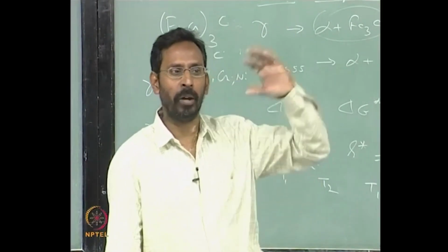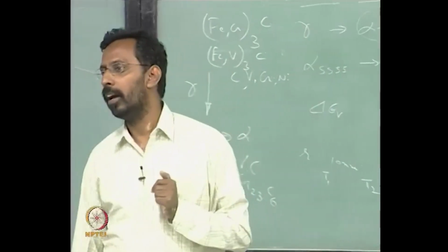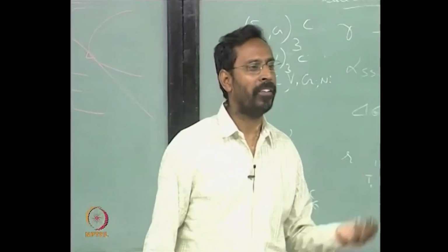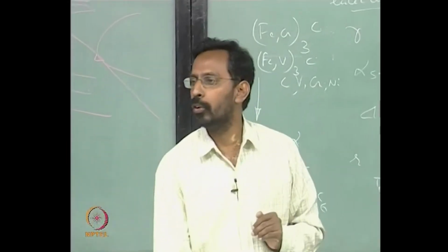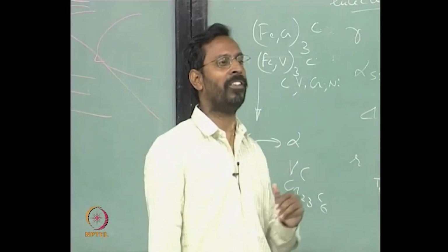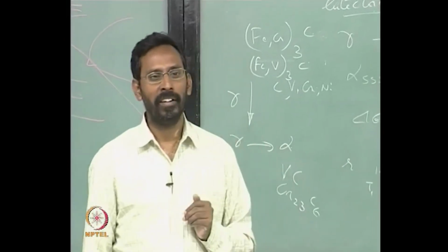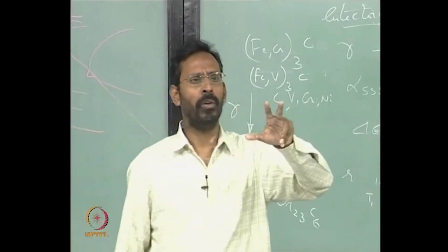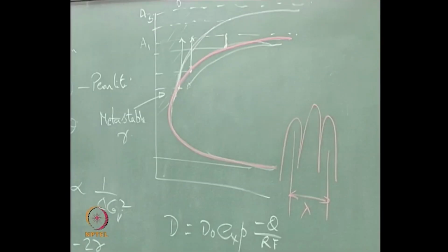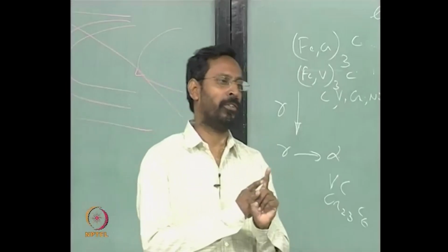At least one plane has a similar arrangement, and more or less the packing factor is also similar. So the cubic alpha structure can nucleate on that, and as a result the pearlite formation becomes easier. Either alpha or cementite, if it can nucleate easily on something already available, makes the whole pearlite formation easier, because pearlite is a combination of the two. The moment one comes, the second automatically comes out.